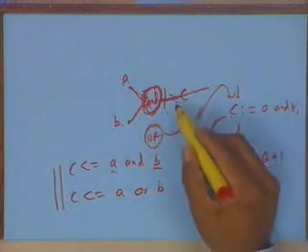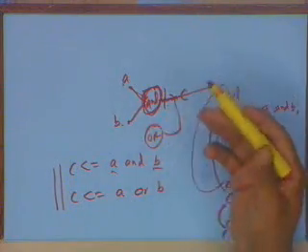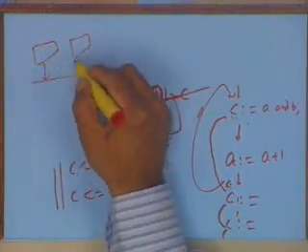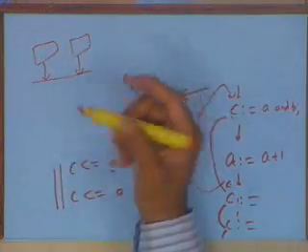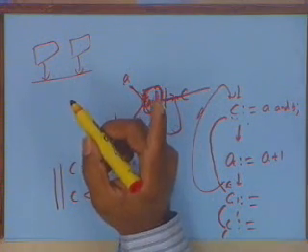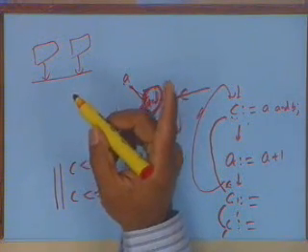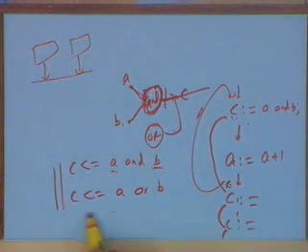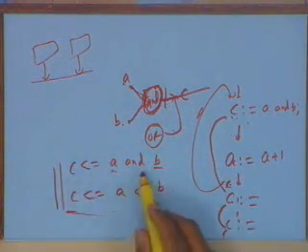We will talk of that later on. So let's say it's a bus. You want to form a bus. There are multiple sources to the bus. But if there are multiple sources, there has to be a way of resolving the conflict. At any given time, there should be only one source. So all that has to be specified, otherwise you cannot specify just multiple.